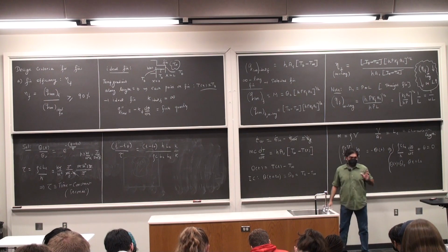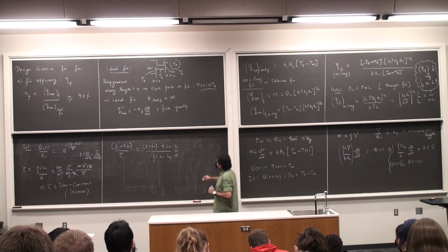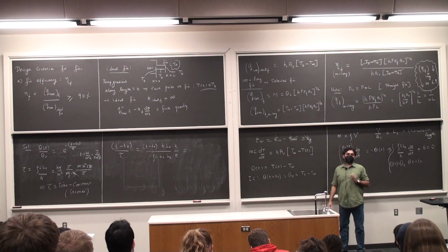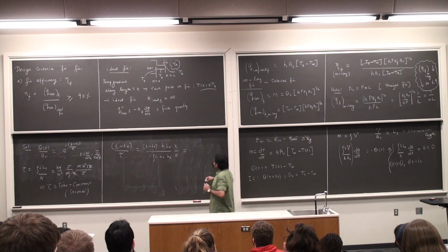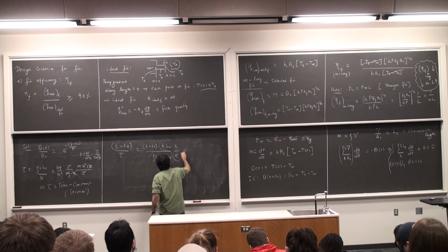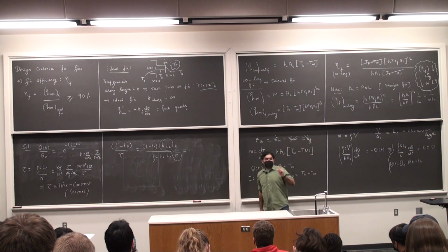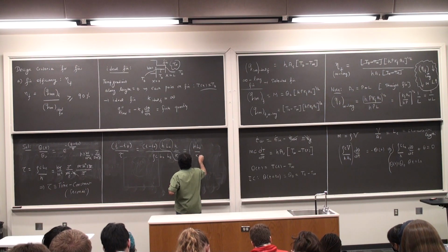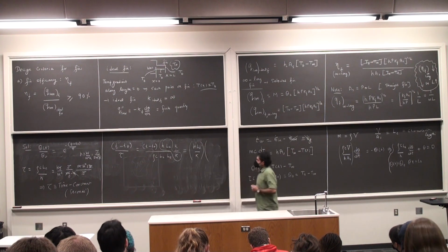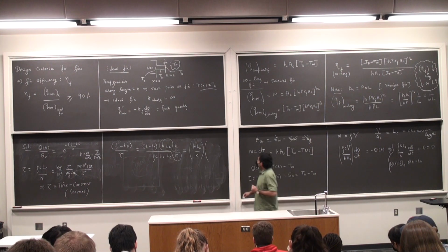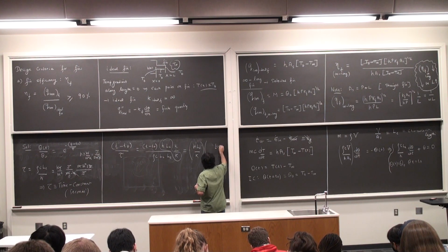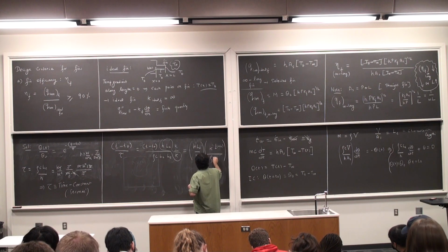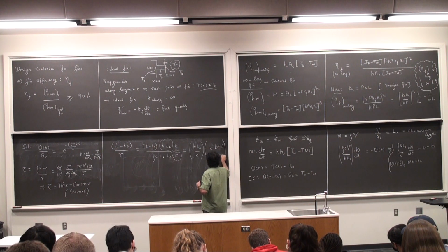And I'm going to group these things in a nice way. Okay? So we did not do anything earth shattering. Everything remained the same. But I'm now going to club them together in the following manner. Take these guys, combine them together as one single parameter. So this is going to be h Lc by k. And the rest of them is (T minus T naught) times k by rho C Lc square.